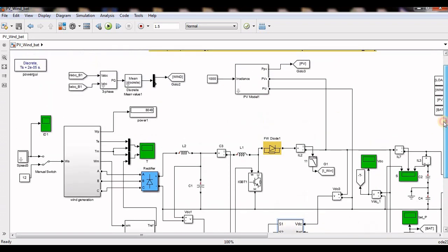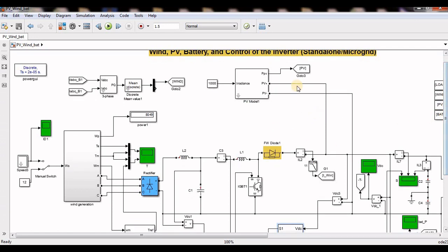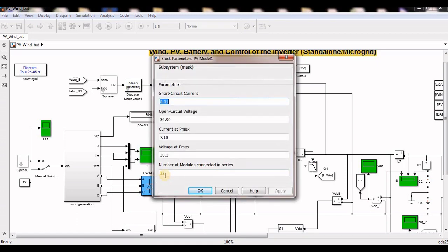You need not connect any other MPPT circuits, which would add more cost to the system. So if you want to connect an MPPT converter separately, then you can manage it. But in that case, you should not select 22 cells because 22 will give exactly 666 volts.